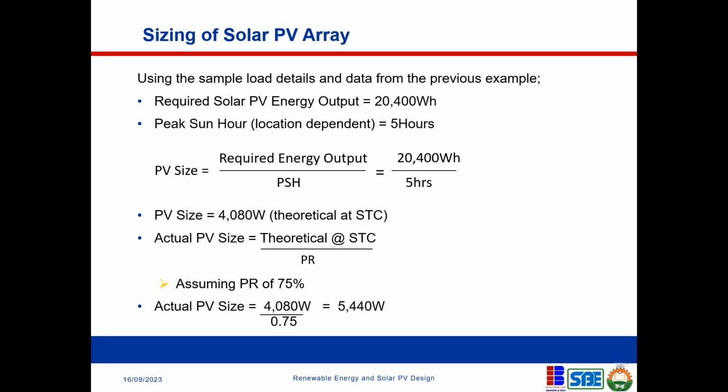Yes, correct. If you look at the technical details of a PV module, there is a graph that they usually show you about degradation. So PV modules degrade over the years. Some will tell you that the PV module has a lifetime of 25 years. It does not mean that after 25 years the PV modules will stop producing. No, it will continue to produce, only that their performance ratio at that point would have reduced to maybe about 20 or 30%.